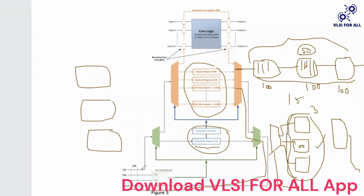We need two things whenever we need to program a certain register. Suppose I need to program the bypass register, or device user data register 1. I need to do two things. Firstly, I will have to load this instruction register, and second, I will have to load the data into this register. So one operation is called the IR operation, and one is called the DR operation. IR means loading the instruction, and DR means loading the data.